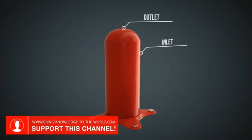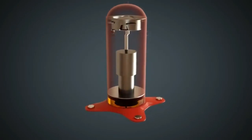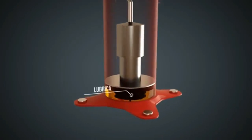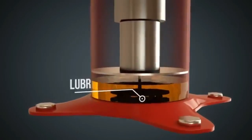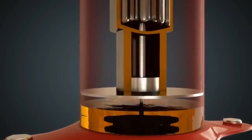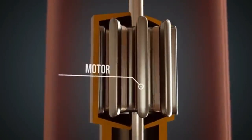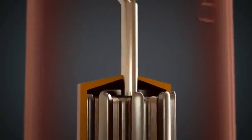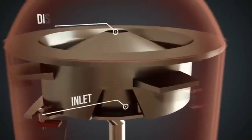A scroll compressor is also known as a scroll pump and consists of a shell with an in and an outlet. The lower part of the shell contains the lubricant, which is used, for example, to lubricate the plane bearings. A motor sets an Archimedean scroll, which is found in the upper part of the shell, in motion. The scroll housing has an inlet, as well as a discharge port, and a fixed scroll.